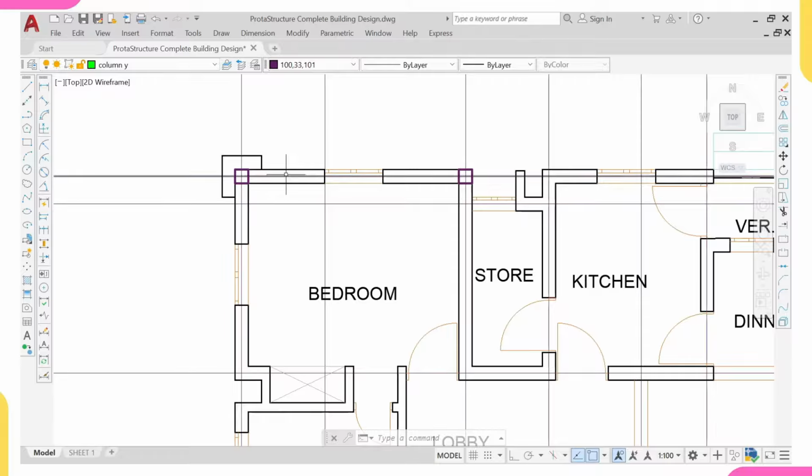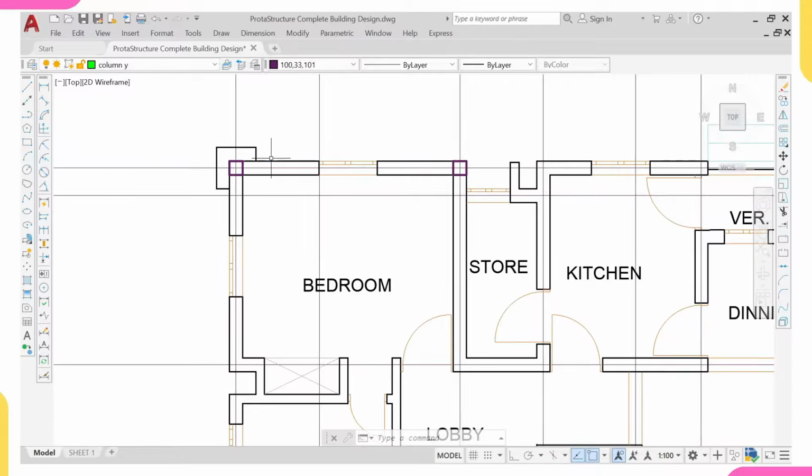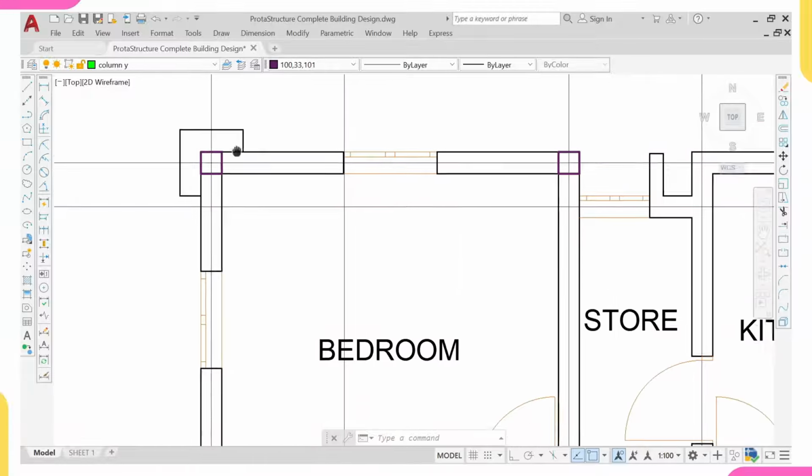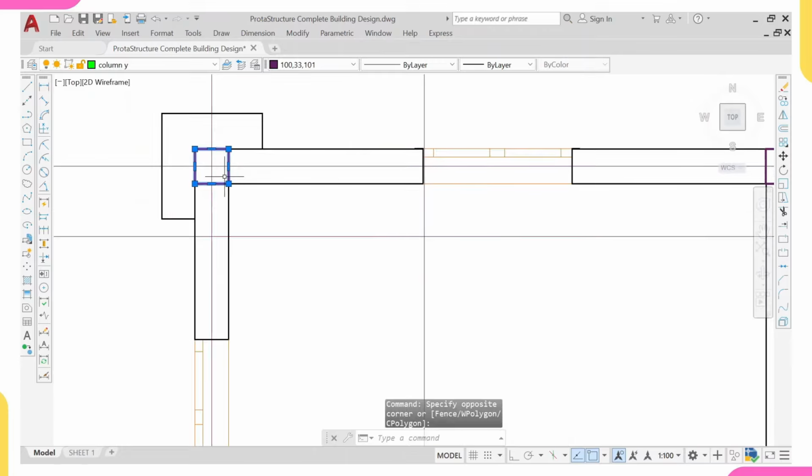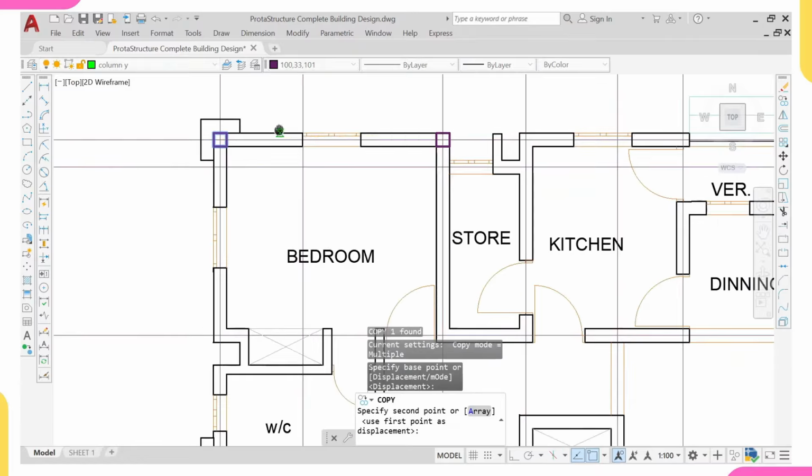So make sure that, but this is only applicable to solid slab. We have different types of slab: solid slab, waffle slab, flat slab, and even hollow core slab. But this is only applicable to solid slab. It is not applicable to flat slab, and it's also not applicable to waffle slab. So make sure you limit them to 6 meters to avoid high moment on your beam. But don't worry, we'll still explain this more during our structural framing in the course of this video.